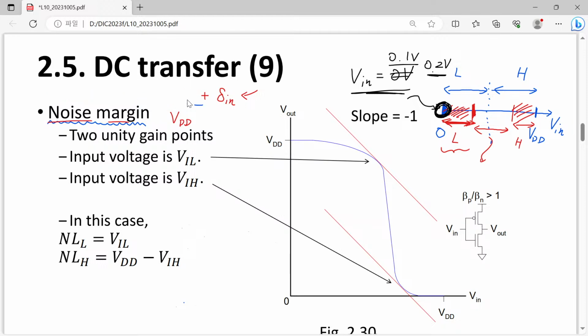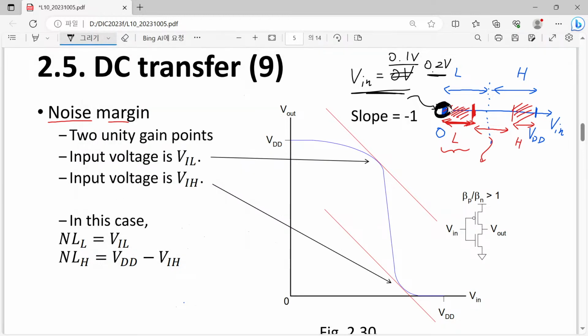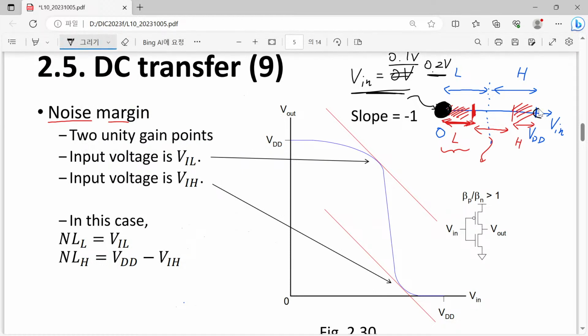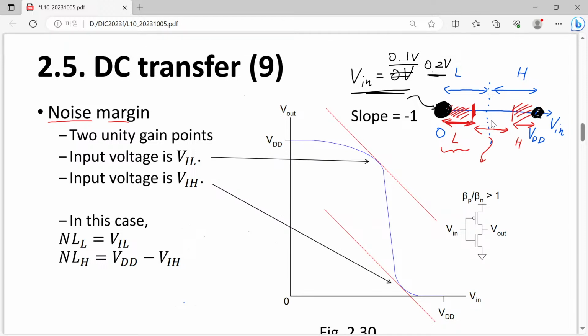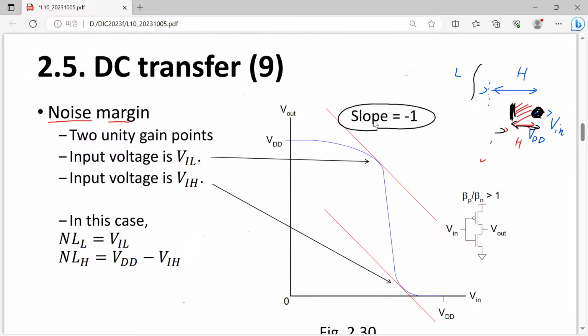So that is one. Then obviously the starting point is quite clear in this situation, because a CMOS inverter always has the nominal output of 0 and VDD, and when we consider just a certain width, we should be able to point out the borderline between safe logical low and the gray region, and the borderline between the gray region and safe high value. How can you define it? We just define this borderline as a point with slope minus unity.